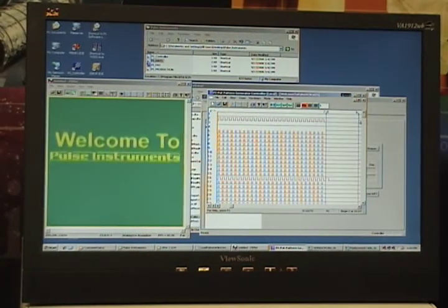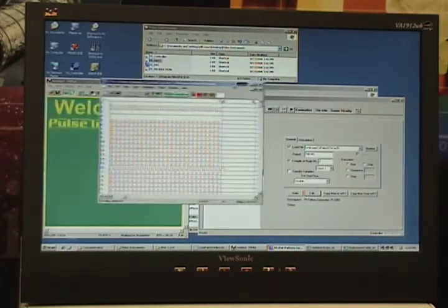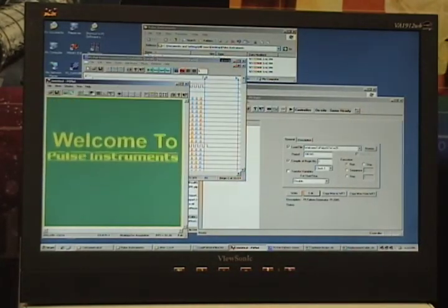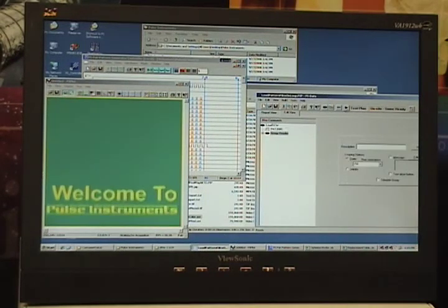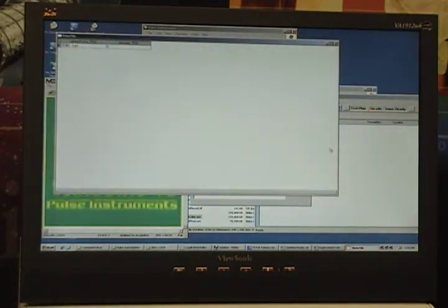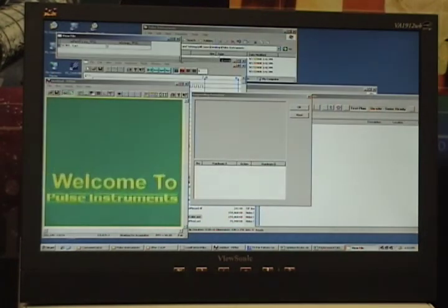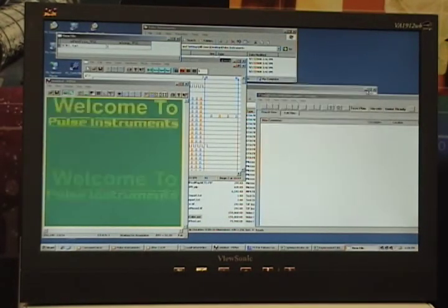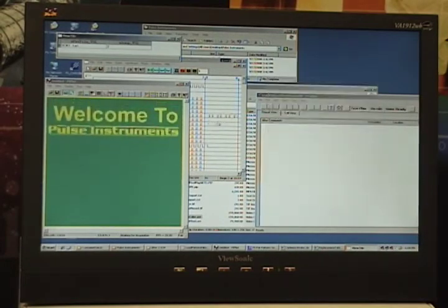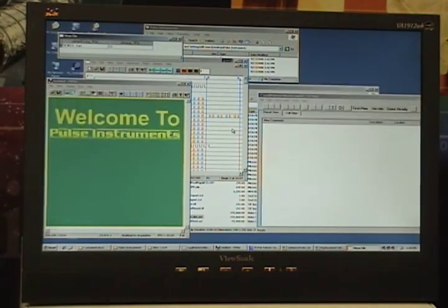I'm going to run the same test pattern that I've been using, and this time I'm going to load a different serial word into one region of memory on each loop. If you look at the pattern memory here, you can see that the values are changing on each loop. This can be used to perform a parametric sweep of integration time, on-chip gain, windowing, binning, or any other device parameter that is controlled by a serial word.